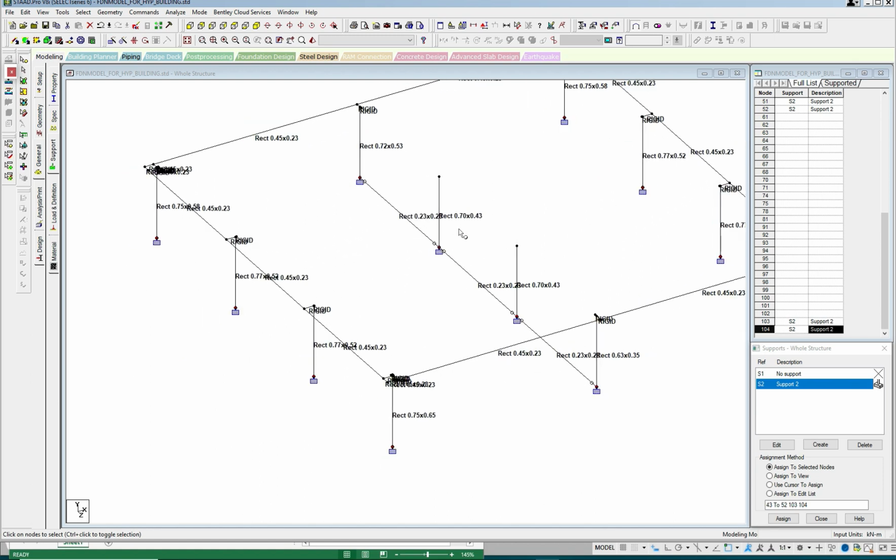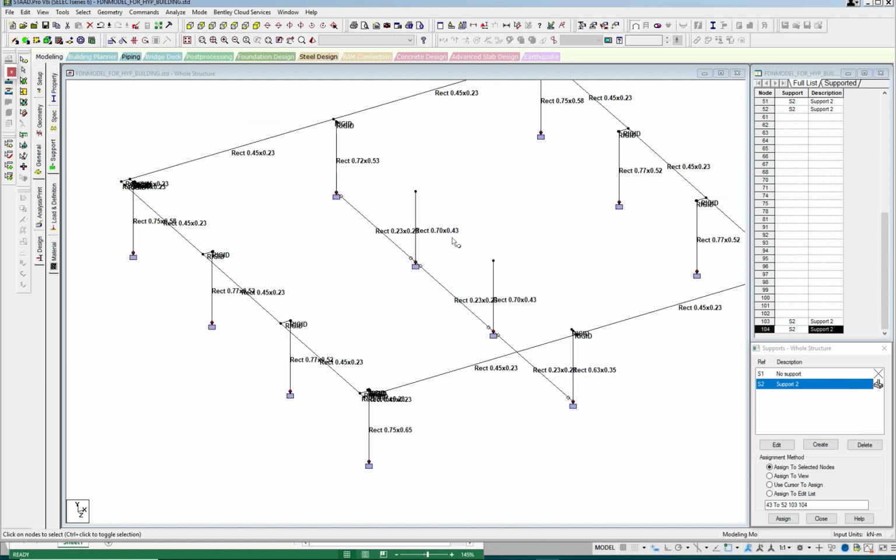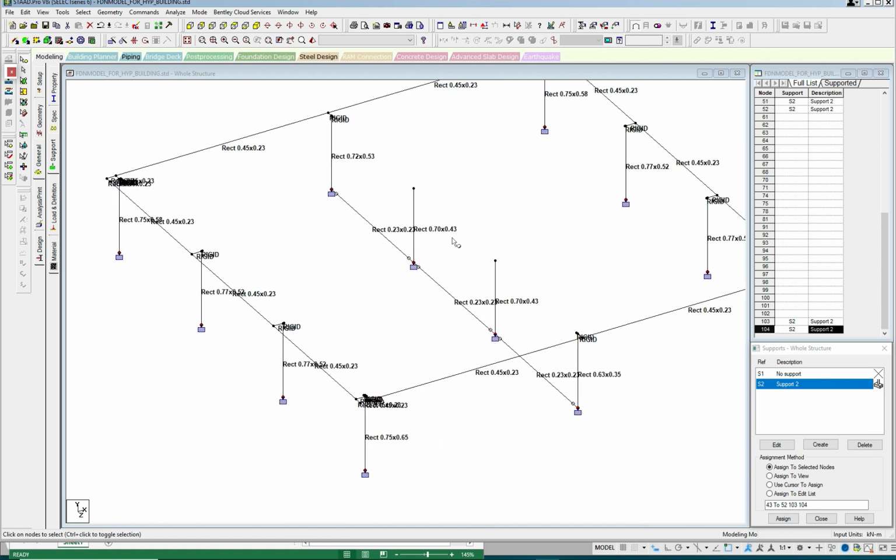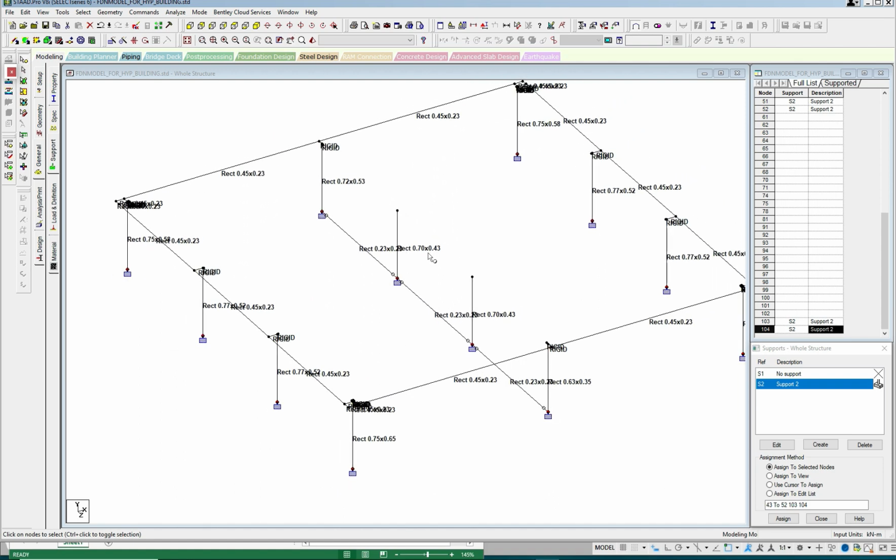So bearing capacity is given with respect to the minimum of allowable settlement or shear failure of the soil. So if you maintain the bearing capacity within allowable SBC, our footing will not be subjected to settlement greater than the permissible settlement.